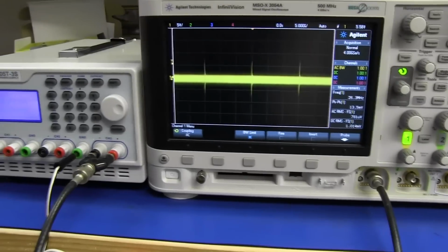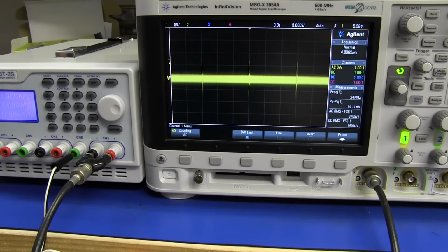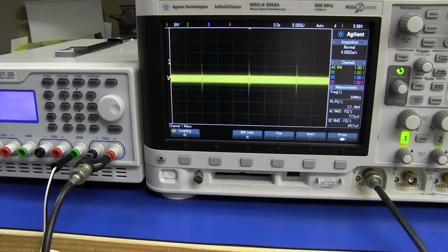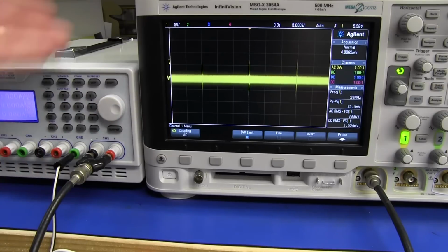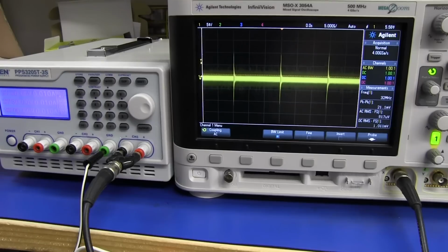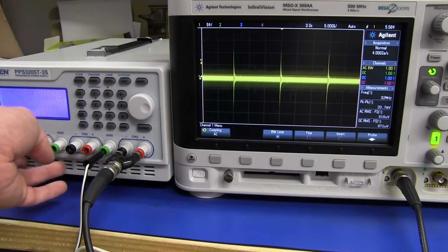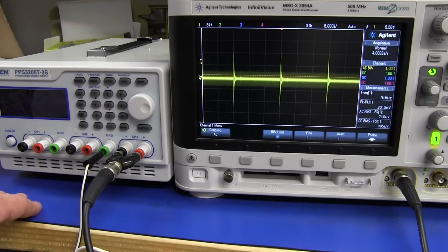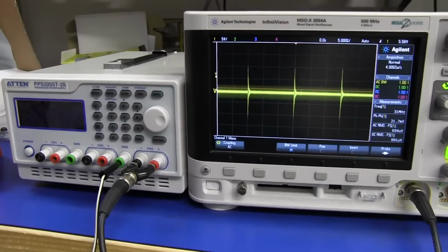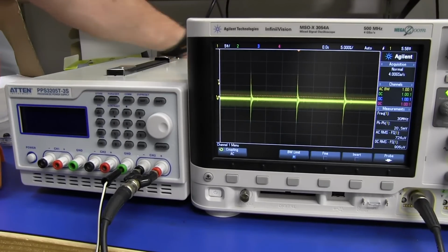So what we're going to do now is, is there any other lab gear around here picking up noise? Maybe this coax isn't that good, right? Is it picking up noise somewhere because it's not shielded all the way in? Maybe it's picking up noise somewhere else. Well, let's try a very simple thing. Let's just switch the power supply off and see what happens. Aha! Look at that, folks. It's still coming through. It's being picked up. What do we do next? Let's pull the mains plug on this thing.